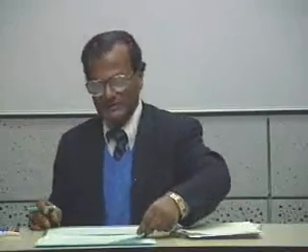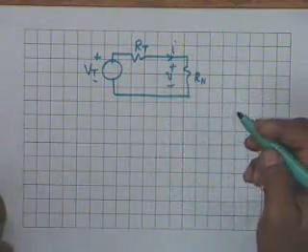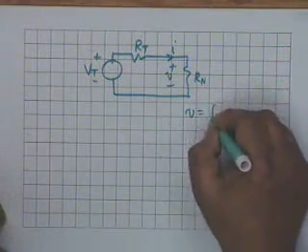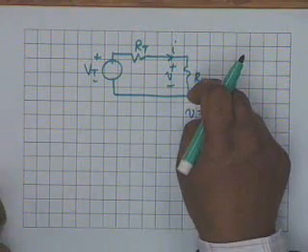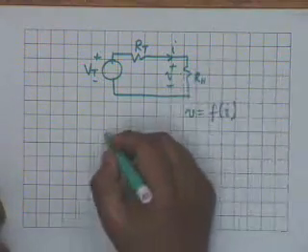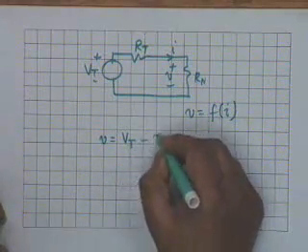If you look at this circuit, once again, the Thevenin equivalent Vt in series with Rt, then Rn, V and I, you see that one of the relations that V and I have to satisfy is that V equals a function of I. This is because of the constraint by the nonlinear resistor. This is the nonlinear resistor characteristic. You also notice that V must be equal to Vt minus I Rt.